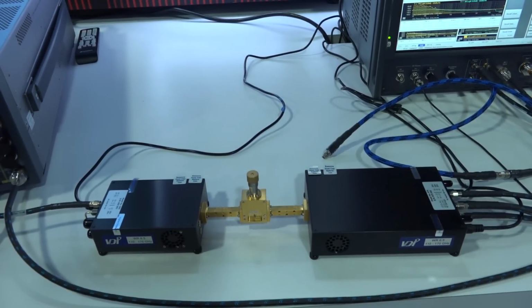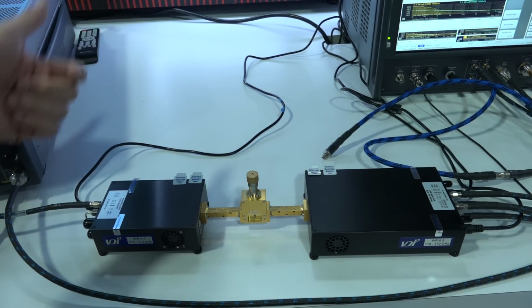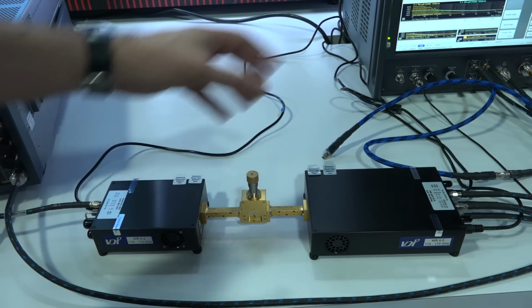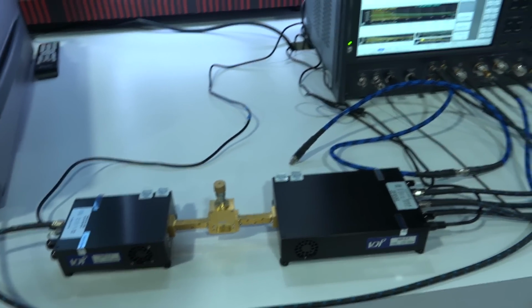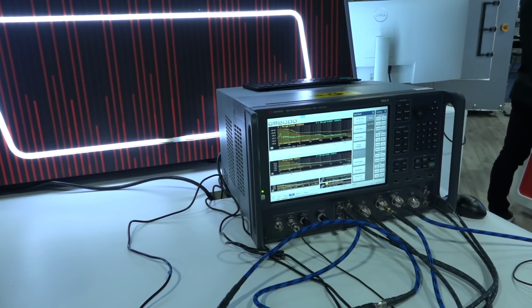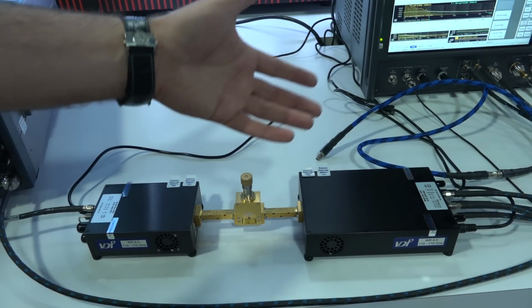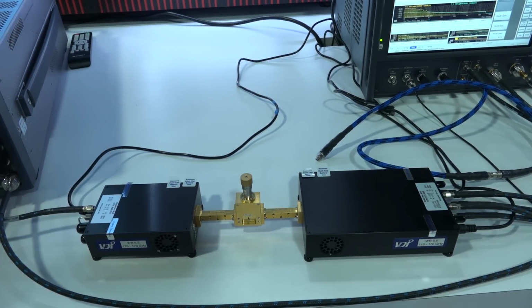But on the other path, we're doing an up and down conversion. So we're taking the 12 gigahertz, going all the way to D-band, and then going all the way back from D-band, and then putting that into the instrument. So you can imagine this multiplication has a penalty on the phase noise of the signal, and then we can de-embed that penalty directly on the signal source analyzer as well. So this combination is powerful because you often don't know what happens to your signal in such complex multiplications, and you can de-embed all of that.